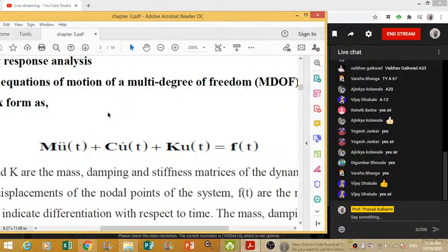Say at first second 10 Newton load is applied. After 9 seconds the load on the component is 100 Newton. After 1000 seconds the load on the component is 50,000 Newton. So this is the drastic change in the application of load, and there you should prefer the transient type of analysis.